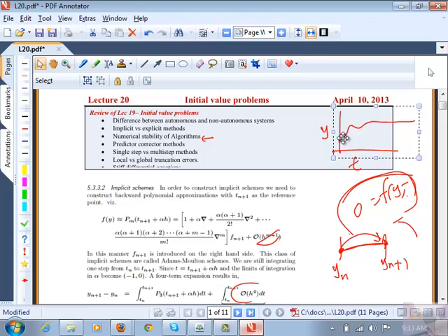Otherwise, the iteration will never converge, and you will see the error going down and up, down and up like that. So there is a similarity between the dynamical integration of a dynamical equation and an iterative way of solving a steady state equation. The pseudo transient method is often used to find steady state solutions. The reason the steady state solution will be accurate is because the part of the truncation error that has to do with the derivatives all goes to 0, even though the step size is fairly large. So we'll still be able to get an accurate result.